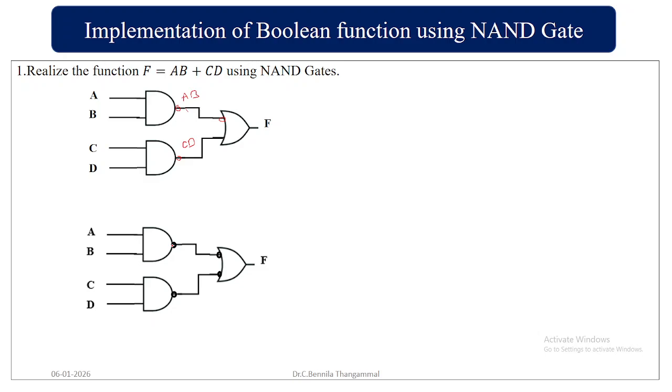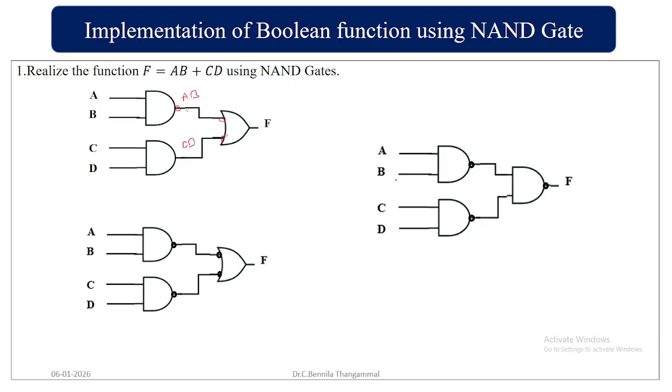And here this OR is going to have the bubbles, right? The compensation bubbles I have given already. Now the second step is to convert your OR gate to a NAND gate. Invert OR is nothing but your NAND gate. Here only one OR gate is there, and its two inputs already have inverters, so I need not introduce anything here. Automatically this invert OR will be your NAND gate. So now all the gates in this logic diagram are NAND. This is called a NAND implementation.